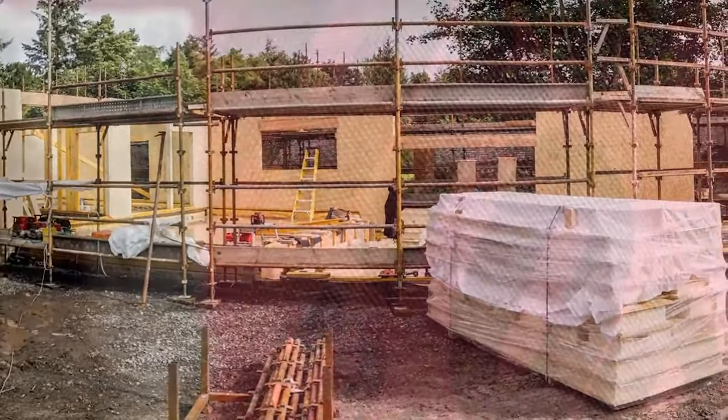So simple things like not assessing the site before you buy it. You mentioned the foundations. You can't accurately budget for a build without checking the ground conditions for bearing capacity, so knowing what the foundation system is going to be, or how you can get power onto your site. If there's a telegraph pole in the next field, that isn't enough to make sure that you can actually get power to it. We've had quotes for new power from anything from $5,000 to 120k. So that's a tiny little thing that somebody can do at the very start to check.